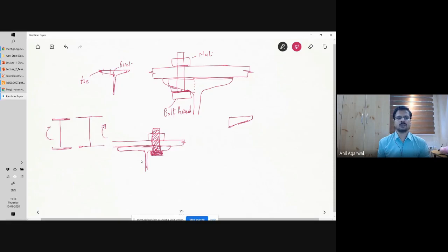In this case, the bending moment capacity against this moment was much higher than the bending moment capacity against this moment, correct? But in this particular case, if I call this Mx and this My, the capacity or stiffness in the two directions are not that far off. In the narrow beam they are very different. Oftentimes you can see that this moment capacity will be almost 8 times or 6 times higher than this moment capacity. Same thing with the stiffness. But in this case, it will not be that different. And that may often be desirable depending on the application.